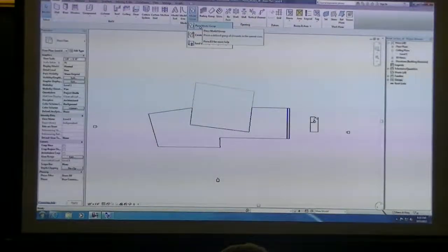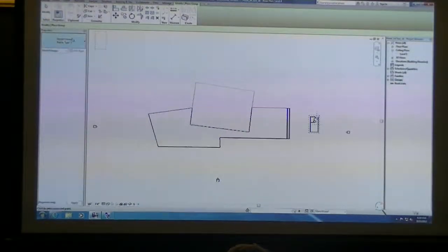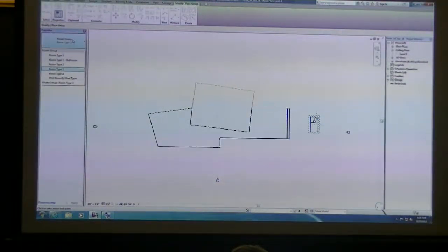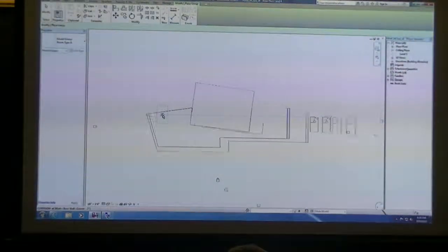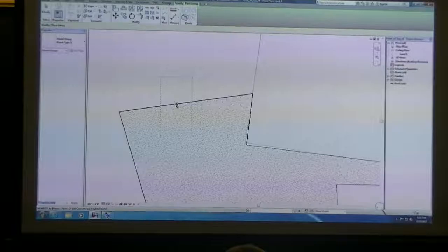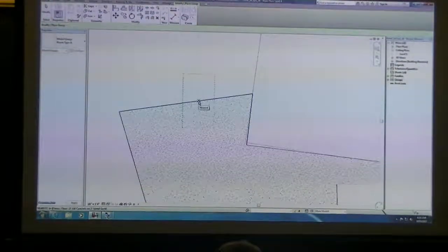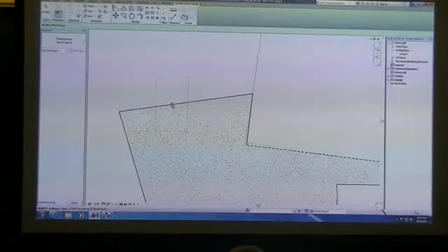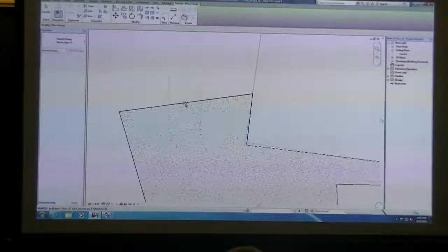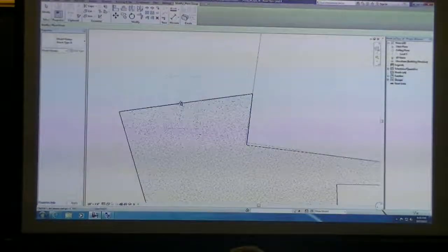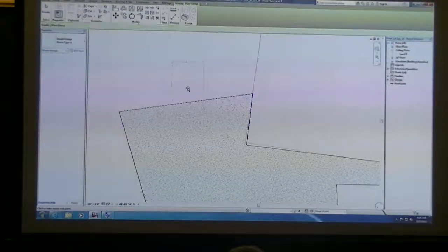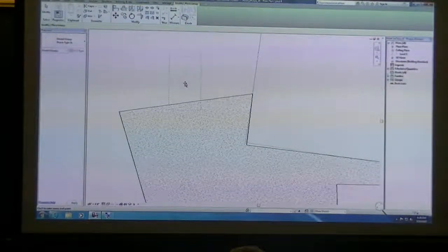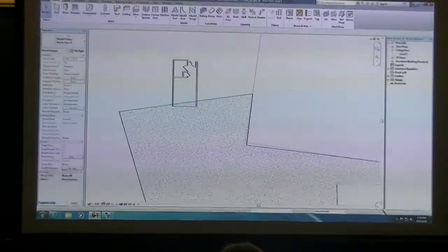So right now I can just click on place group, and this works just like the families. I've got this pull down bar in the properties section, and then I can find all my model groups, and I can choose room type A and then place it. But I don't have the controllability like when we place the door. Remember I said you would hit the space bar and it would rotate the door around and also align to certain angles that are already established. Right now basically I can't rotate it, but I can just place this actual room at the moment.